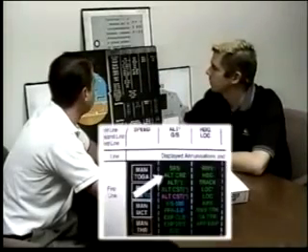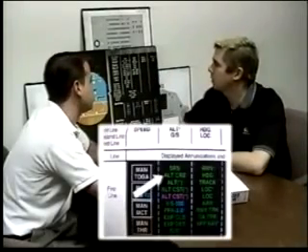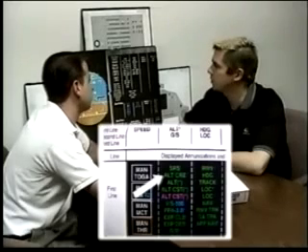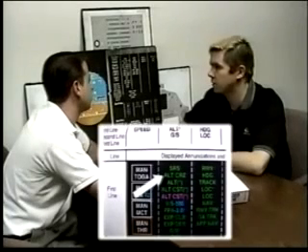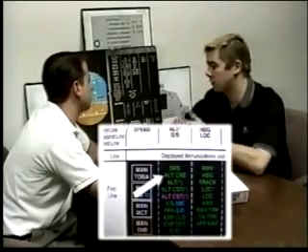What about alt cruise then? Well, alt cruise is basically the same thing. It's an alt hold, but instead of just engaging the altitude at the FCU, it's going to be engaging the altitude that's in the FCU as well as the cruise altitude set in the MCDU. Big difference between alt cruise and alt, though, is alt hold, or alt, is a hold at a specific altitude. Alt cruise, though, gives you a plus or minus 50-foot window that allows the thrust to be a little more stable, which supposedly gives the passengers a smoother ride, or a more comfortable ride.